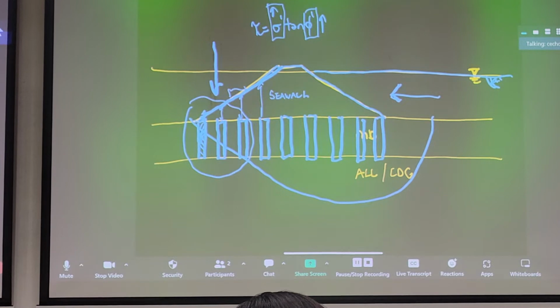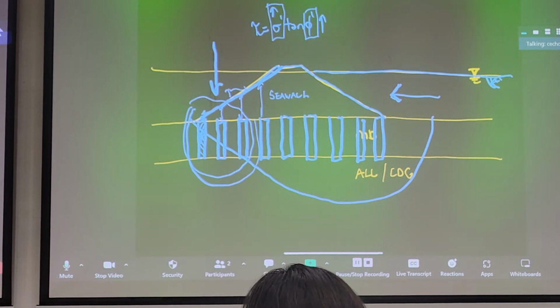So these kind of designs do exist, and then you have to ask yourself, does it make sense to have almost no overburden to mobilize any shear resistance here? And if we have a failure mechanism cutting through the leading edge of the seawall, is that problematic? Is that dangerous, right? Because your seawall can settle. Often for reclamations, we also use the seawall for transport roads as well. So this is sort of a contradiction, I think, in using stone columns. We should try to mobilize as much shear resistance as possible inside a stone column.